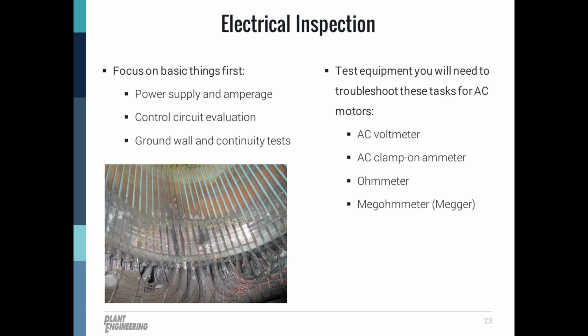By using a voltmeter, we could first check for applied line voltage at the power supply of the motor at each line to ground to eliminate any potential blown fuses. And then we could proceed to test each phase, line to line. The applied voltage could be direct wired from a simple on-off switch, or it could be coming from somewhere a little more complex, such as a VFD or soft starter. So when performing these tests from a control circuit such as a VFD, we will want to ensure that the proper power is available at the incoming and outgoing side of the unit when in run mode.